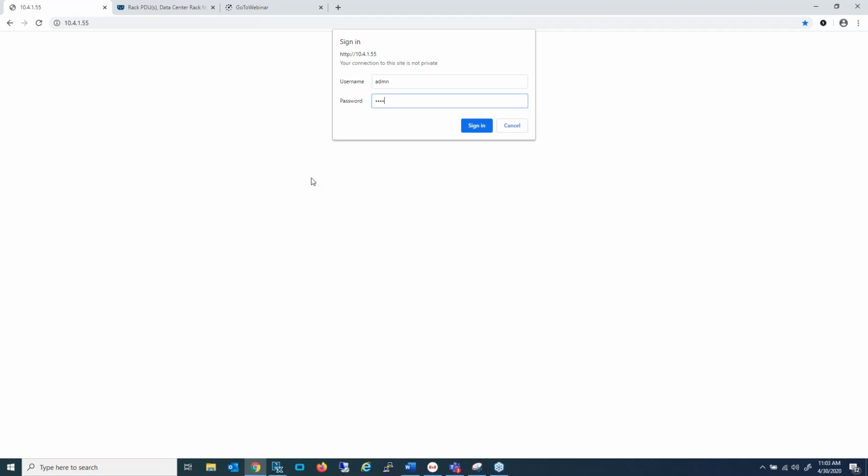Today's topic follows nicely. Today we will discuss how to remotely identify amperage capacity for a specific PDU. We will learn how to view the real-time current, the amperage measurements at various points in the system, and how to set amperage thresholds to receive alerts if an overcurrent protector is in jeopardy of being overloaded.